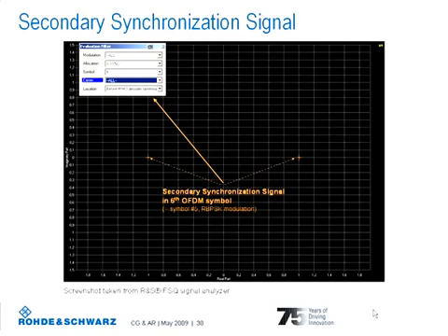Looking at the constellation diagram showing now the secondary synchronization signal, we believe to see a pure BPSK modulation. In fact, the secondary synchronization signal is represented by an interleaved concatenation of 2 length 31 binary sequences. These 2 sequences are scrambled with a scrambling sequence depending on the physical layer identity, which is transmitted with the primary synchronization signal. So without finding the primary synchronization signal, the terminal cannot conclude on the secondary synchronization signal. The combination of the 2 used sequences defines the physical layer cell identity group.